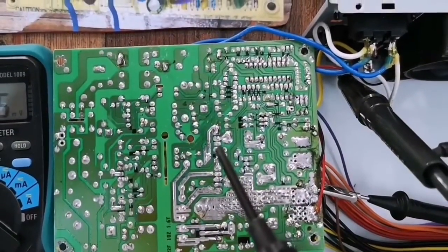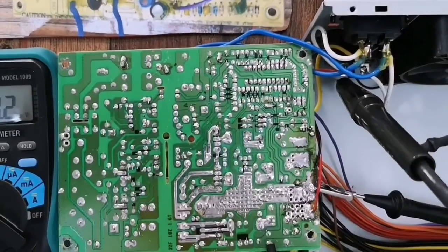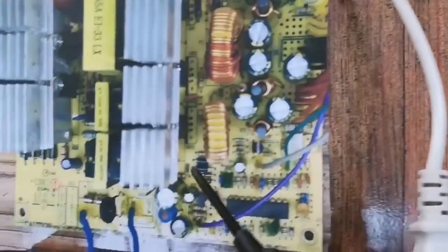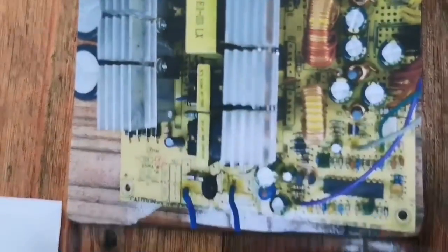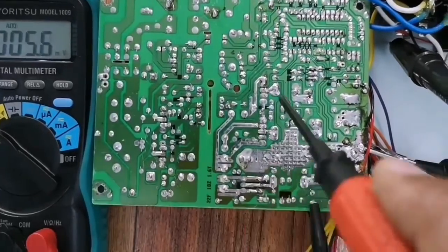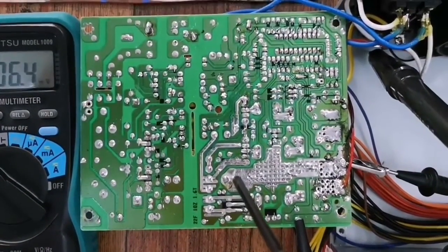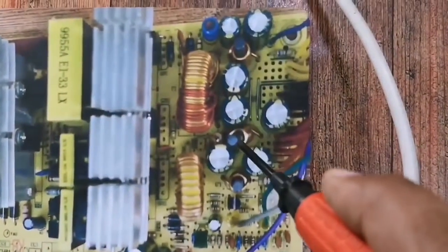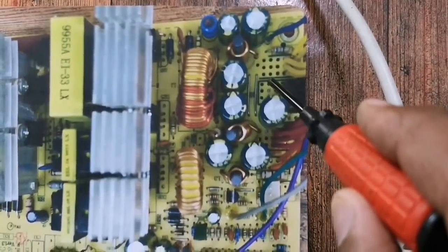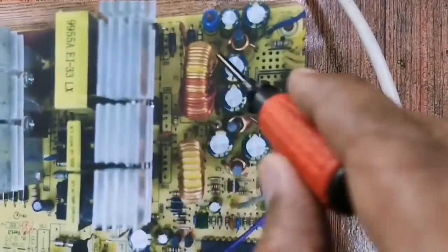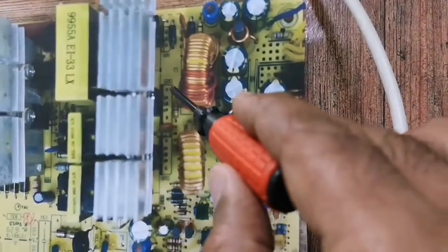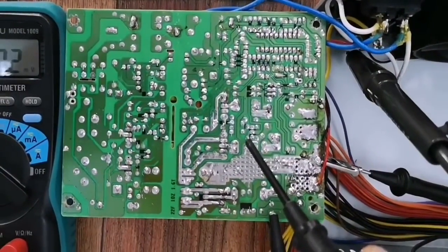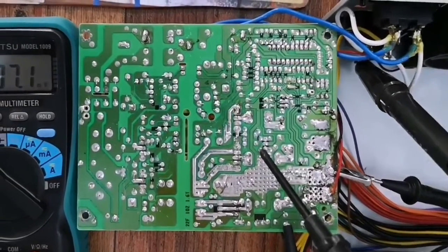And I can guess this is happening now because of undervoltage at the output, because we found the main switching transistors are off and no voltage is generated at the other side. And I don't expect an overcurrent condition for mainly 2 reasons. First one, I have already checked the components at the output voltage side before, during power off, for short circuit, and none is short circuit.